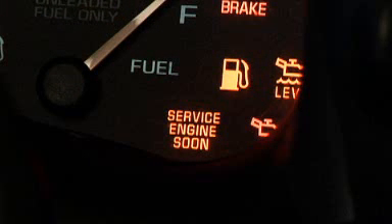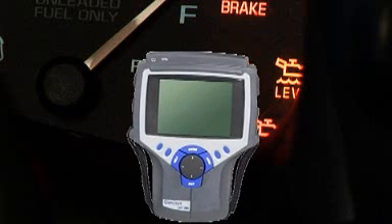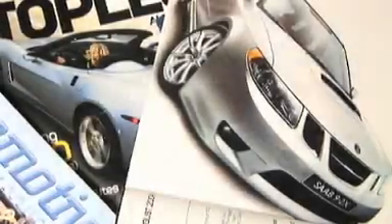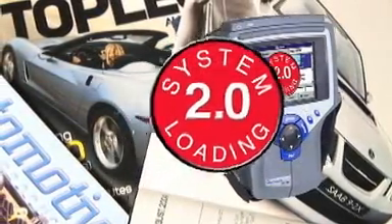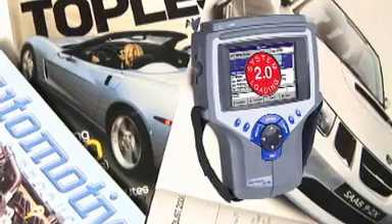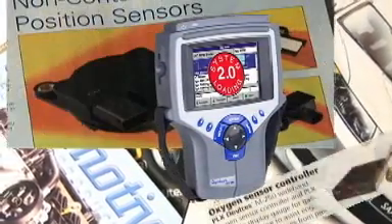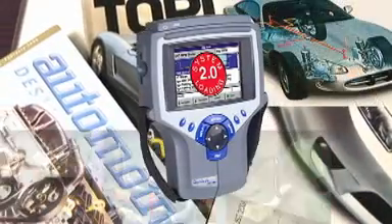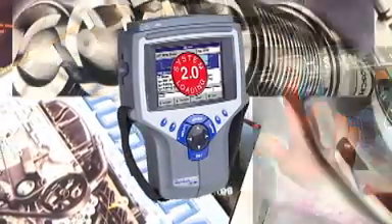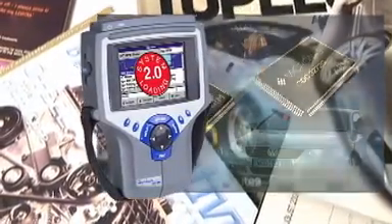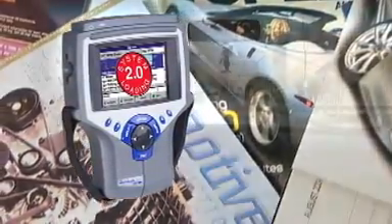The diagnosis on vehicles with the check engine light on typically starts with the use of a scan tool. But a scan tool may only take you so far in the diagnosis. A scan tool will tell the technician which circuit is at fault, as the computer has recognized it. But he cannot necessarily tell if the fault is in the sensor, connector, or wiring leading to the computer. It is here that the technician needs to use something other than a scan tool to isolate the exact problem.